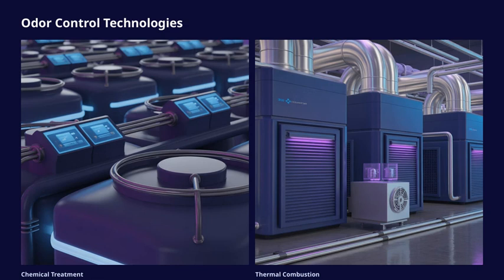First up, chemical treatment. Sodium hydroxide is a common chemical used to control sulfide generation. It works effectively at a pH of around 12.5 and can keep sulfides in check for a month or even longer. When using odor removal towers, it's important to remember the recommended organic loading rate, which is about 0.5 pounds of BOD per day per cubic yard of media. This helps ensure the system is working efficiently and not overwhelmed.